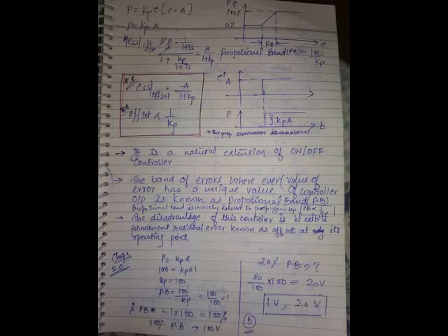Let us see how this fellow is going to work. The controller output is 1 by Ti integral of A dt, because E is A. It is A by Ti into T. This is the response of the controller. This is how he is responding. A by Ti into T.